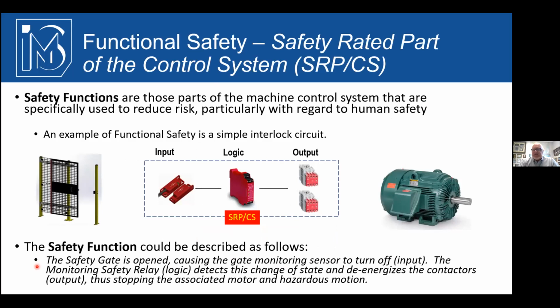And the safety function becomes an entity in and of itself. When we talk about the performance of a safety function, we're talking about the performance of the entire element. This becomes one specific element, not just the performance of each individual item in here, but this all becomes the system. So this could be a valve as well, a pneumatic or hydraulic valve versus a motor. This would be valves here, or pneumatic actuators and hydraulic actuators.